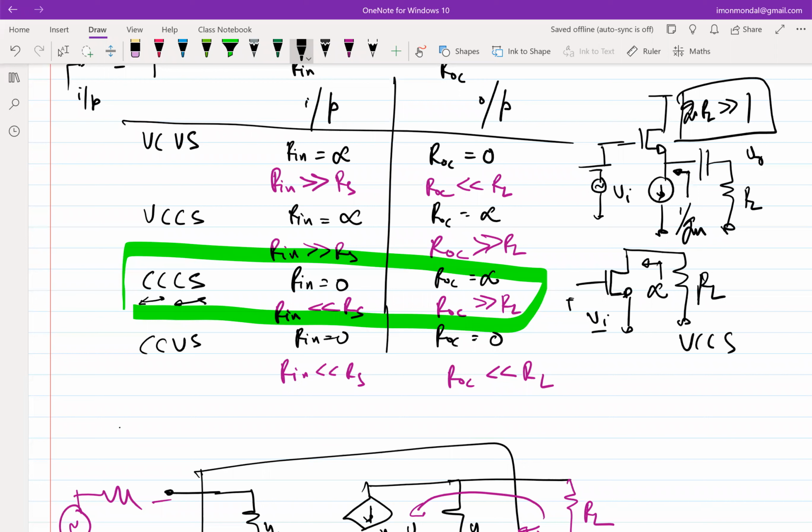Yeah, so sometimes you cannot have a current source, you put a large resistor or some sort of resistor, then obviously the inequality will change. In that case, the output impedance looking in will be 1 over GM parallel the resistance that you have put in place of the current source, which has to be much less than RL. So let's turn our focus to this CCCS.